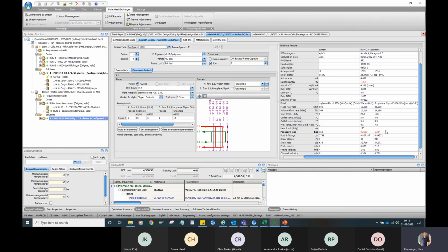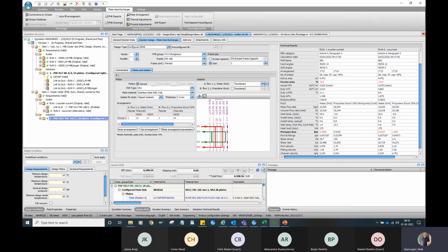But you can come into cases where you need to go into a co-current flow regime, and that is if you're, for example, cooling water like here. And if I just try changing this glycol temperature, then you will see that the wall temperature gets close to 0 or underneath 0.